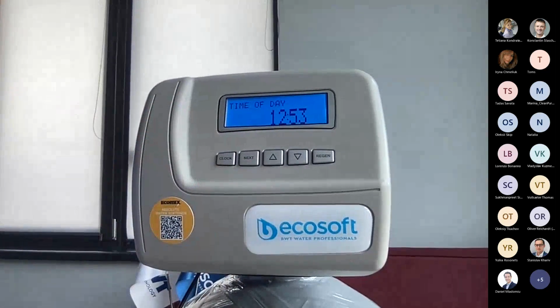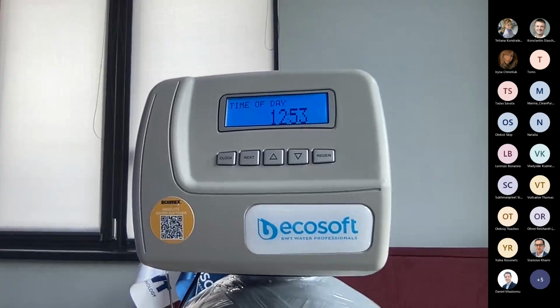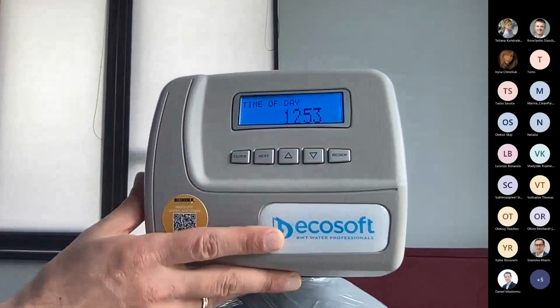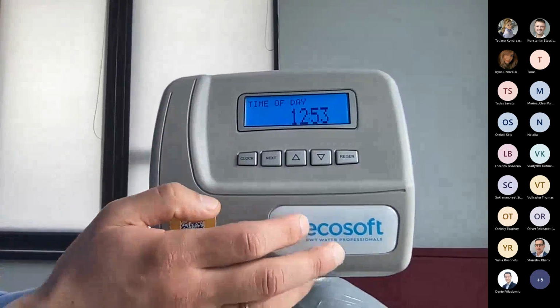When you have done all the programming and all the changes, sometimes you are a little bit frightened that someone would come to the valve and change the programming, by accident or just by going through the steps, and then you would have to come on site and visit once again just to fix the possible error. So you may actually lock the keyboard by pressing a combination of buttons.